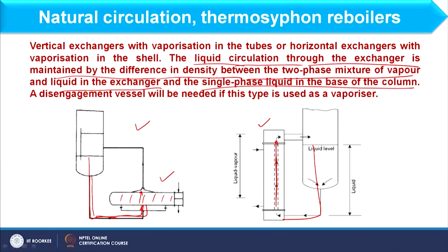If I consider this schematic, whatever pressure drop available to us, it is available from this to this height, right. So, this we call as the pressure drop available to us. Okay. And when liquid enters into this, it starts converting into the vapor, and vapor liquid mixture moves up, and then it is entering into the distillation column.